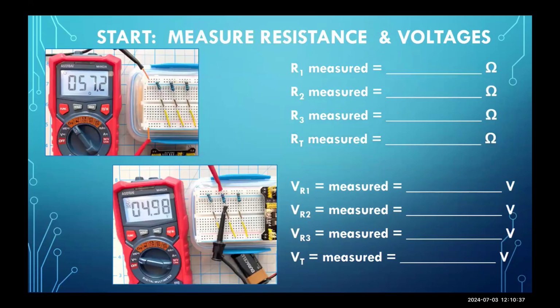So right here, this shows the connection for measuring total resistance. I'm going to use jumper wires, a jumper wire attached to the blue rail to one of my hooks, and an orange jumper to the red rail attached to the other hook. And you say, well, wait a minute, Co. Why do I have the black hook of my ohmmeter attached to the red rail? Why do I have the red mini hook attached to the blue rail? Aren't these opposite of each other?